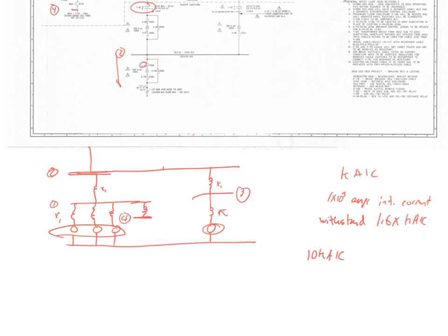So there's no current flowing in it. Grounding it isn't going to change anything. If you have a balanced current going into a Y, and the balanced current sums at the neutral, how much current has to go into the ground? Zero, because it's balanced. So whether there's a neutral there or not, the balanced system doesn't care, because it sums to zero. It couldn't care less if there's a ground or not. It's irrelevant.